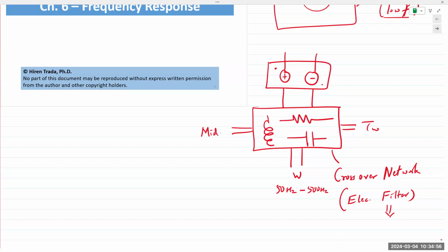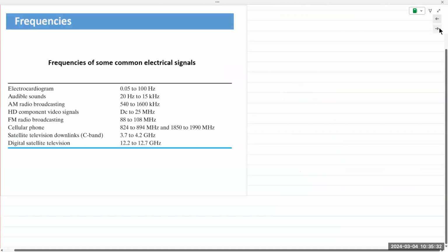Remember, chapter 3, DC, constant voltage, inductor behaves like a short circuit. So when frequency f is equal to 0 or very low, the inductor behaves like a short circuit. When it increases, the impedance increases. ZC is inversely proportional, it's 1 over 2πfC. It's 1 over f. So as frequency increases, the capacitor behaves like a short circuit. When the frequency is lower, the capacitor blocks out those frequency signals. There's high opposition. And so that is the magic that allows the filter to work. Well, it's not actual magic, of course.